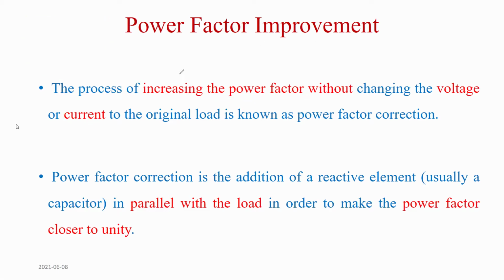So again, increasing the power factor without changing the load. Power factor improvement usually is adding a reactive element, usually a capacitor, in parallel with the load to get the power factor to be close to 1. 1 is perfect. Close to 1 sometimes is what we want.